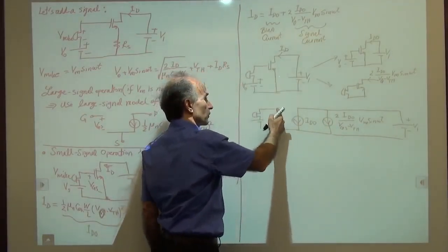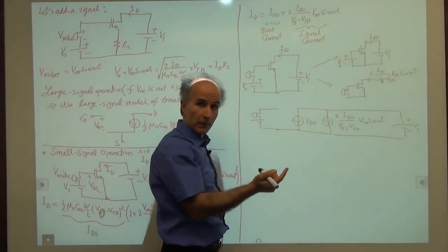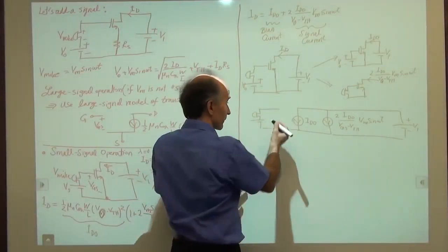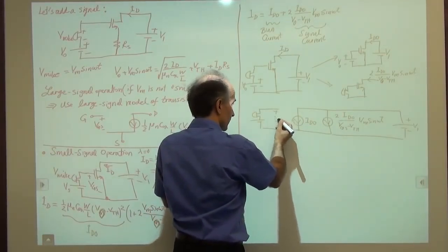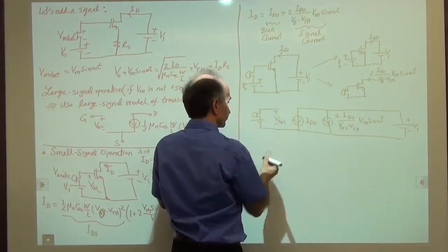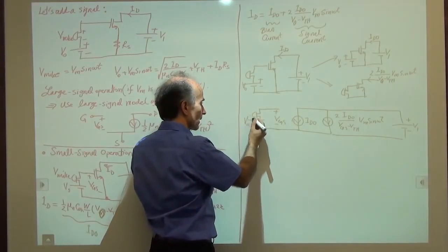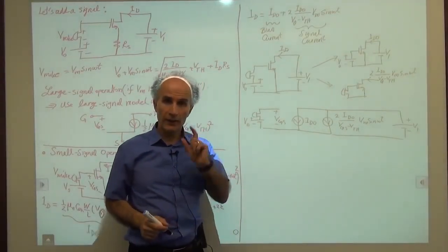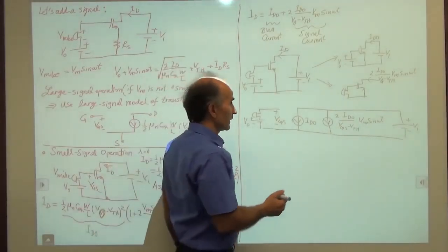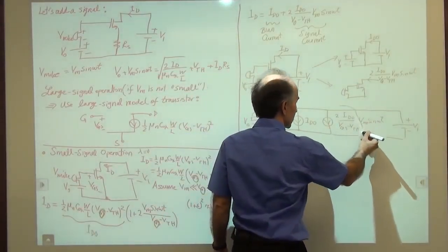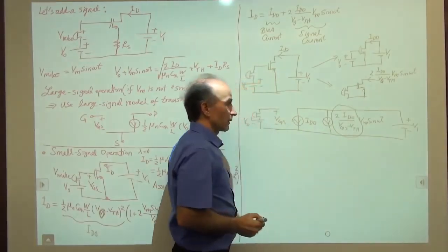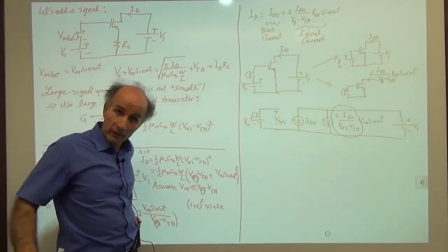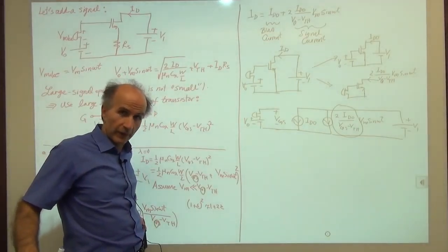Between the gate and the source, we don't have any impedance because the current drawn by the gate is very small. But we still have a voltage here, right? That's the VGS that we have. That's total VGS that we have. Okay. All right. So, one interesting observation. What is this? This factor here, is it familiar? This factor is the following. It's a bias quantity, because there's no signal in it, right?